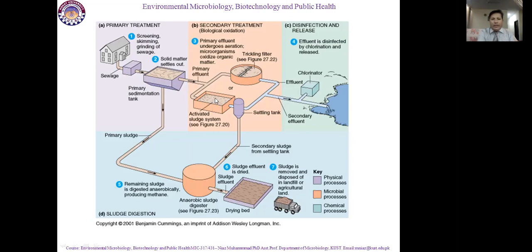Active microbes are present which are responsible to decompose the incoming organic material over here, and they will convert it into their basic elemental form. From here again we will filter the supernatant, which is free from organic material, and it will go to this side, and undecomposable material will travel towards the anaerobic digester. So only pure water will travel to this side.